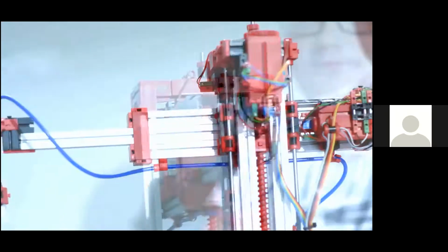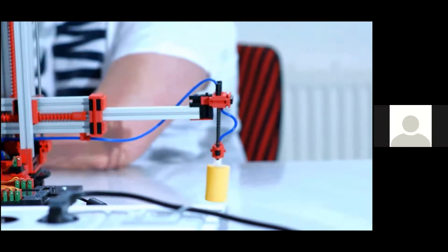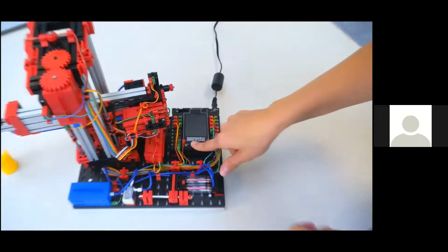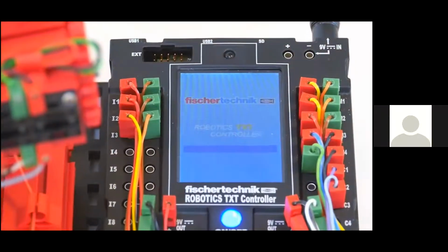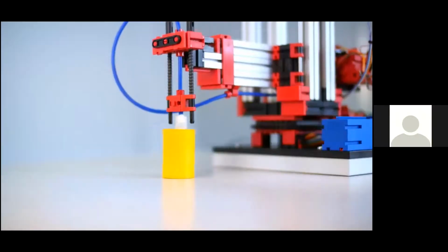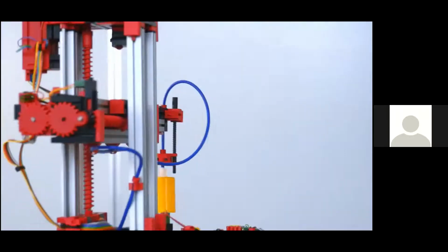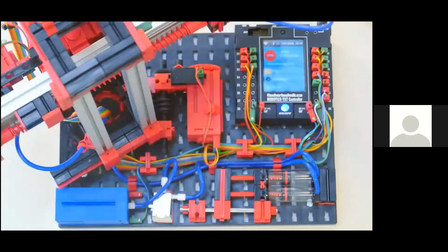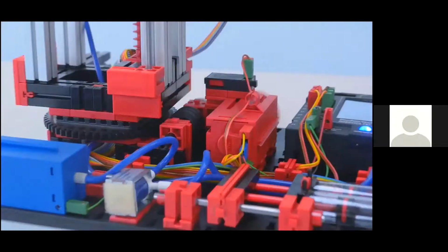The model's dimensions are approximately 9 by 19 by 15 inches, and it has a weight of only about 7 pounds. The 24-volt versions of this model, as well as all of the first 5 24-volt models that we're going to be looking at today, each have a relay board for motor polarity reversal and both a multi-pin connector with 34 pins and a grid of 2.54 millimeters, as well as additional PCB terminals with push-in connections for all inputs and outputs. Again, the 24-volt version of this model, as well as all of the 24-volt versions, will require you to provide the PLC and the programming.